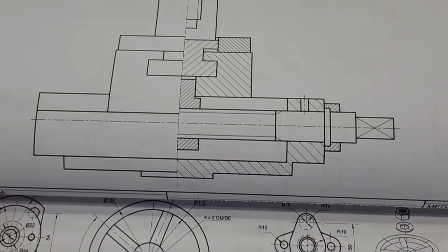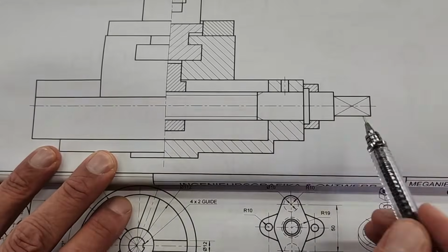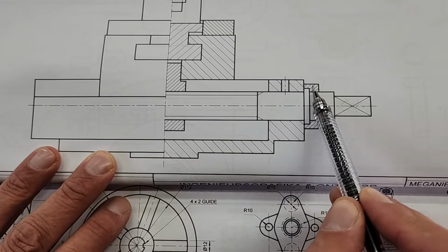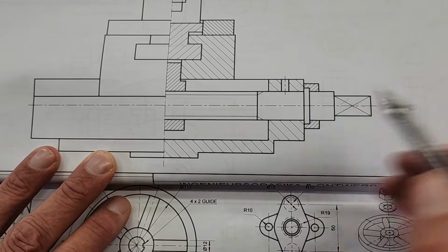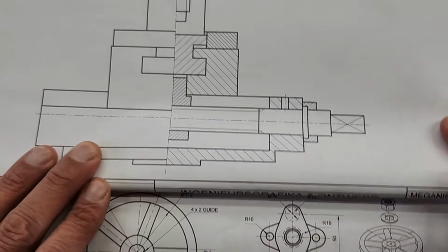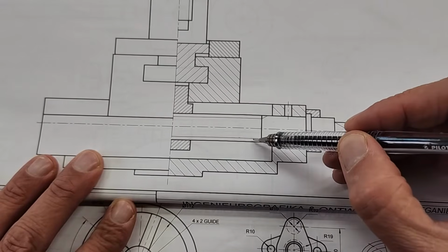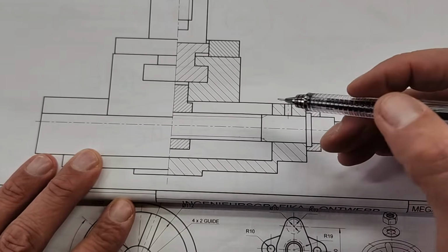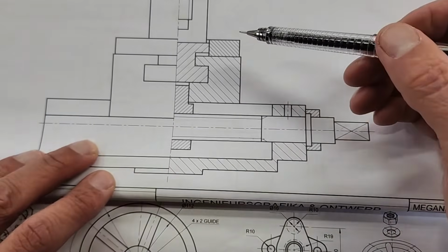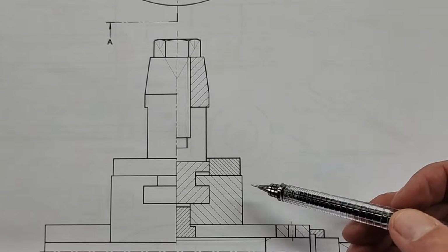Here's another example, just where we look at a square on a shaft, not hatched. Again, adjacent, different hatching is required. Screw threads, shaft, not hatched here. This is an external screw thread, so it's not hatched. If it was an internal screw thread, like in the previous example, it wasn't screwed in, of course, you'll show the hatching there. All right.